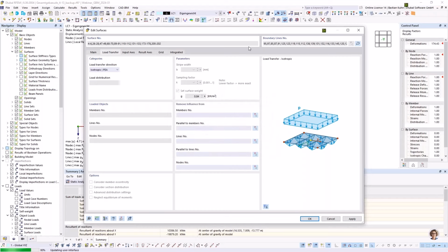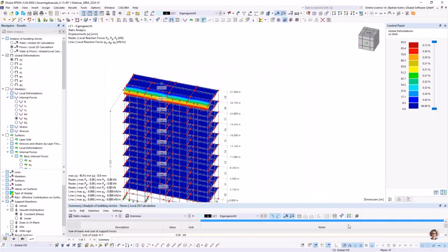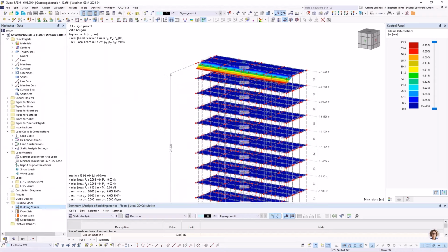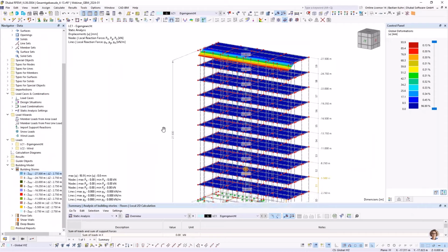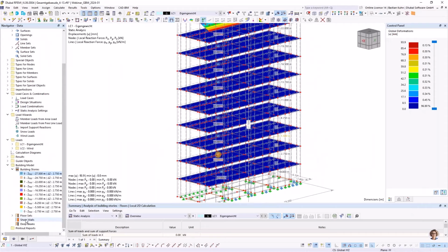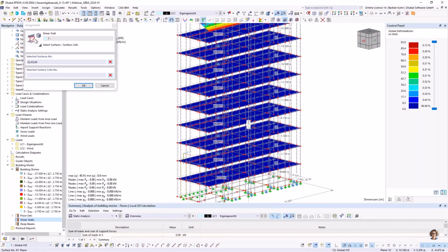and I will calculate only the load case 1. That gives me time to take a look at what the reason was that this is looking so strange. Maybe if I take a look into this, but this is all correct. And maybe I could also activate shear walls and deep beams. It's a function that is perfect for analyzing results, and maybe then it's connecting it correctly. Just to try for now till the calculation runs in the other model.